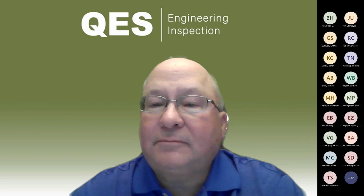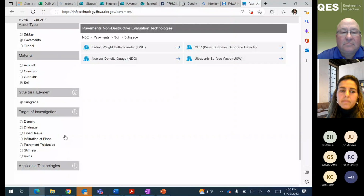Certainly. I was looking at the website, it's really nice. On the non-destructive technologies, we've been using electrical resistivity tomography for some projects. It's really worked nicely to help us with some moisture problems with perched water tables, and then we used it to find some scour debris when we were trying to relocate bridge shafts. So that's another non-destructive tool that we have found useful, and we're finding more uses for it in the highway applications.